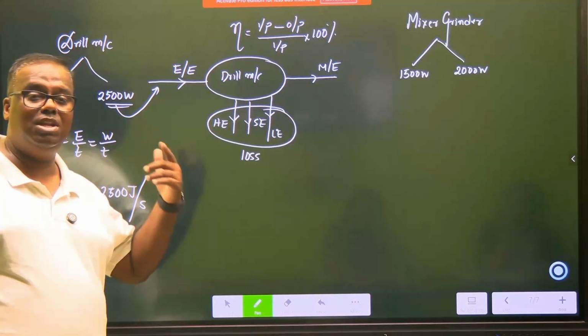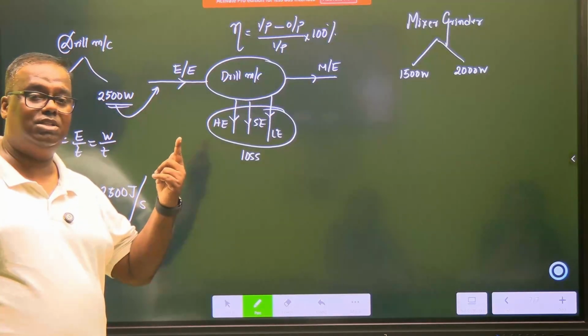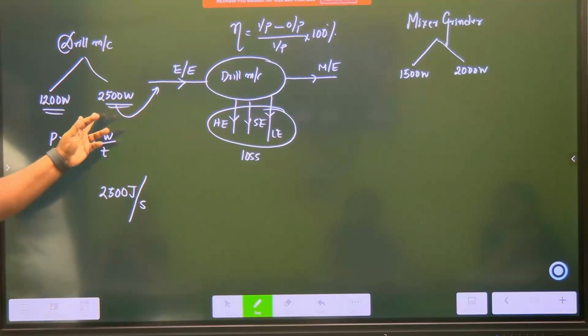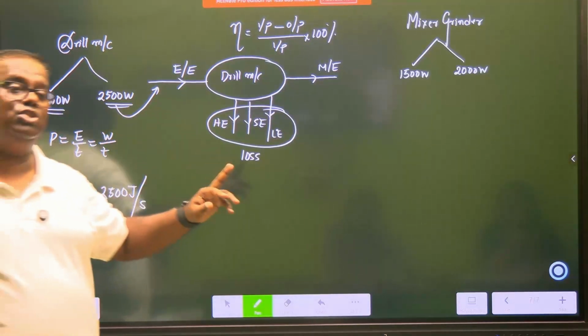And it will scream and yell a lot. Plus the drill bit, since heat will be developed more, the bit will wear out. So you need a heavy machine. A heavy machine will do the job in lesser amount of time.